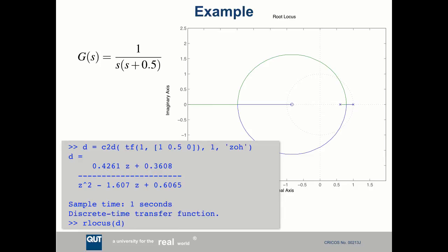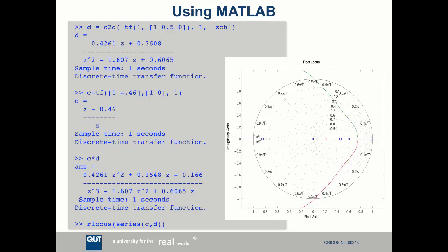I drew the root locus. You can vaguely see the unit circle there. Two poles come together and then they go up, and they stay inside the unit circle for a while, then they leave the unit circle and go around and do the usual kind of pole thing. So I introduced a lead compensator, and by judicious choice of gain, I could move the closed loop poles to where the little squares are.